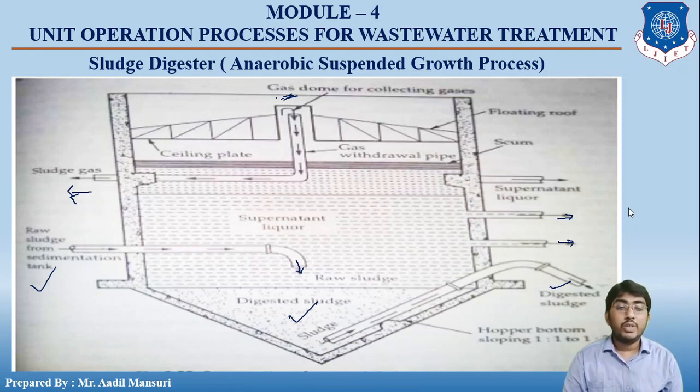Fine. It should be noted that the methane formers are sensitive to pH value, and if their population is not sufficient, then the methane formation process, that is the degradation of volatile acids by them, will be at a slower rate, right? On the other side, saprophytic bacteria will continue producing volatile acids at a faster rate.